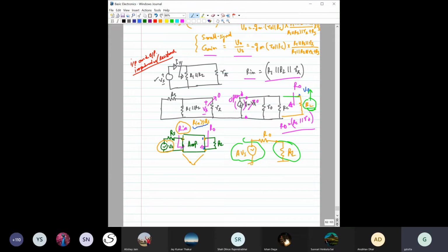There are different types of amplifier. One is called a voltage amplifier. It can be a current amplifier, a transconductance amplifier, a transresistance amplifier, a couple of things. But I think you will agree that there should be no doubt from the input side. And if in the output section you are getting the output like this, the output equivalent circuit, we are not going into much detail about what is inside this circuit, but if the output portion is like this, then you want that RL to be much higher than this R0.